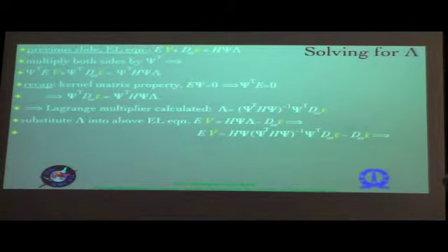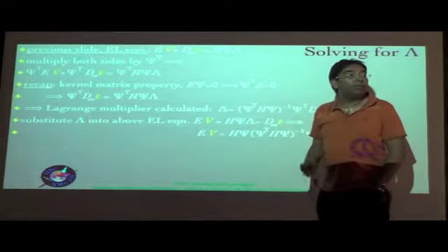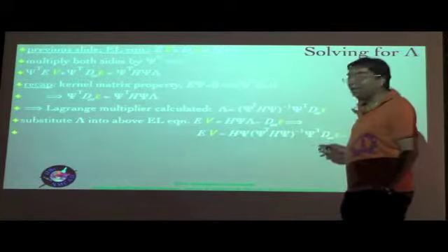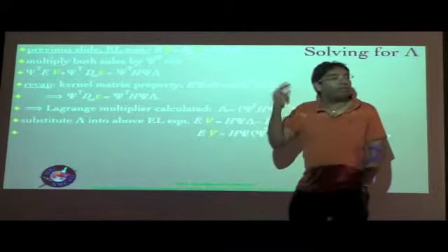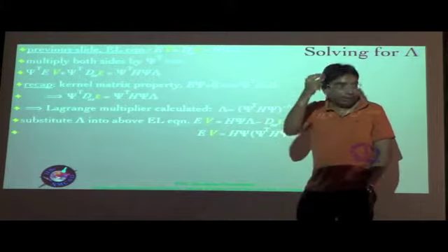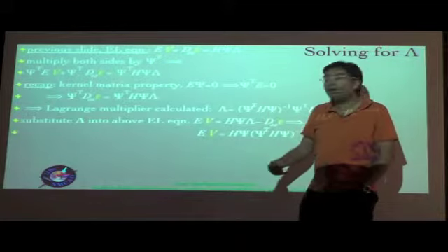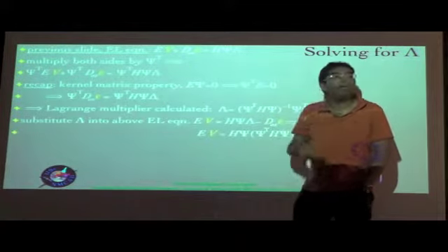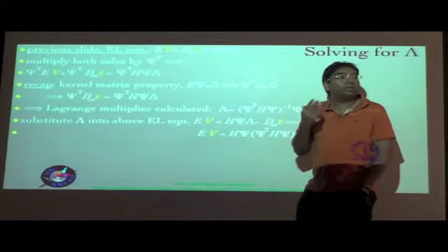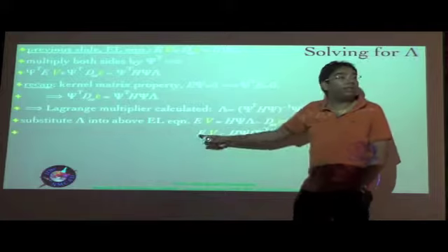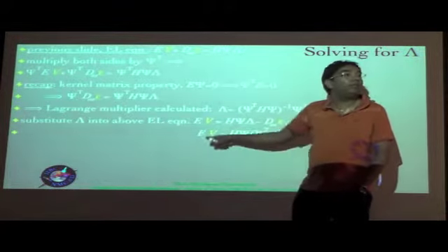This would be a fairly easy thing to solve if you are able to invert E. But remember that though the right hand side has already taken the constraints into account, the left hand side, in the definition of E, the way we define it, has not yet taken the constraints into account. Or in other words, out of the n degrees of freedom that you have, if you take the eigenvalues of E, for example, you will get 4 zero eigenvalues. So in other words, there are 4 singularities associated with E, and therefore you cannot invert E and determine the V.